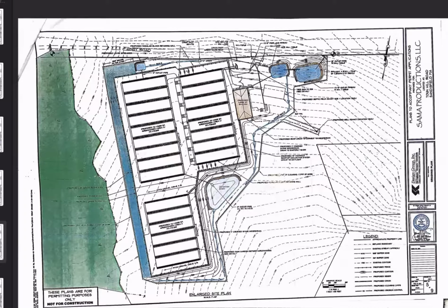Section 8, the next section in your bylaw, talks about driveways. And I apologize, I know it's boring, but this is all stuff that's required as part of the permit application. Site distance: there are about 15 requirements for driveways. I think less than that actually apply. If you go to number 3, it's 100 feet of site distance in each direction. We clearly have several hundred feet in each direction.